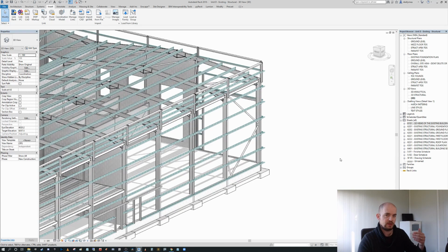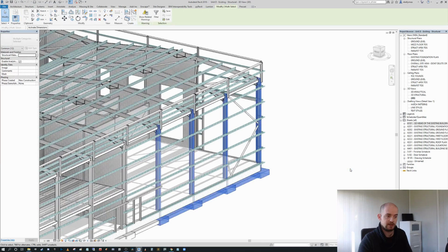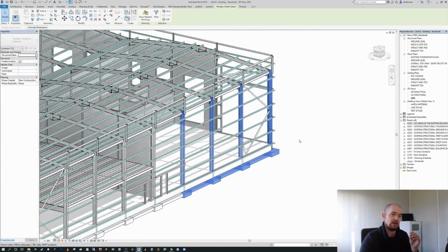If you do nothing else, there's a very, very simple way of regaining that selection. If you right click in space immediately, you can go down and press the fourth option, which is select previous. And there you have your previous selection all there ready to go again. That's a really useful tip, because I can't tell you how often you misclick. It's a massive time saver if you're spending the time to create your selection criteria properly. This is a godsend. So that was number 13, how to reselect your previous selection.